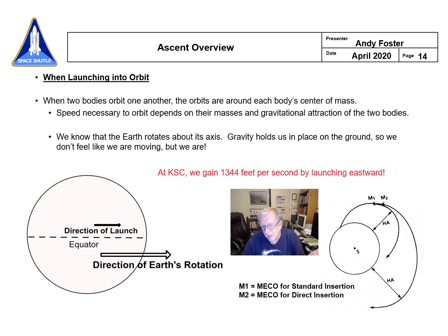The other thing that's funky about orbital mechanics is that wherever I burn, the result of that burn shows up at 180 degrees out, at apogee or perigee. If I start burning a little bit before, then I actually move that apogee just a little bit as well, or move the point where it is in the sky.